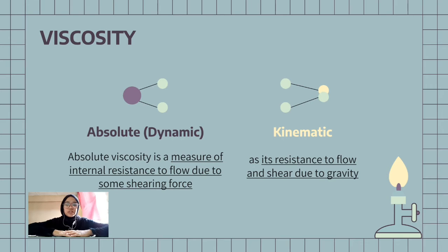First is viscosity analysis. What is viscosity? Viscosity is a measure of a fluid's resistance to flow. A fluid with high viscosity has lower flowability, because high viscosity resists motion due to greater friction when in motion. Viscosity allows us to analyze liquid behavior and fluid motion. Usually viscosity is measured as kinematic viscosity and absolute viscosity.